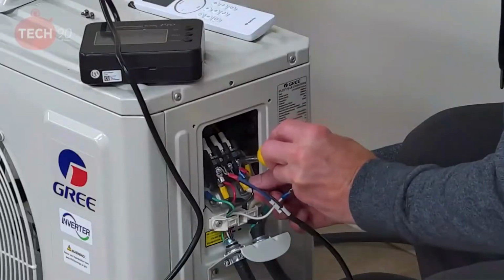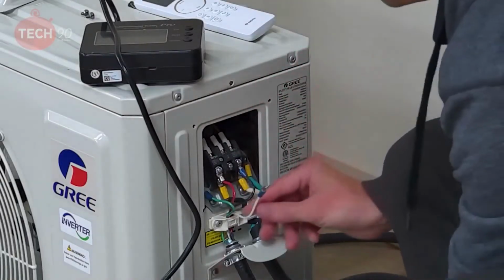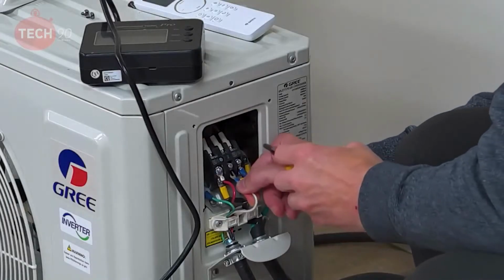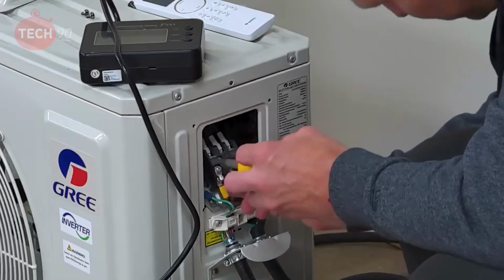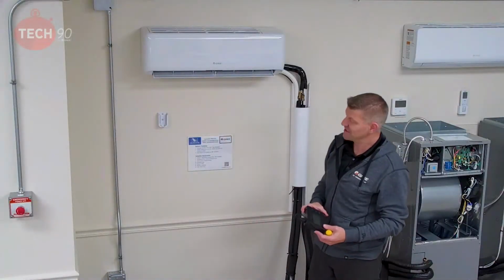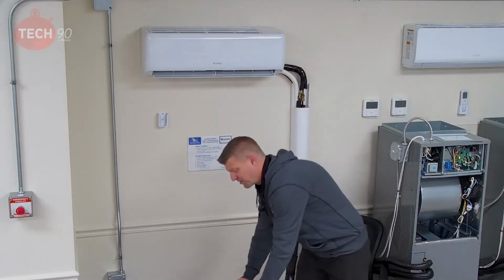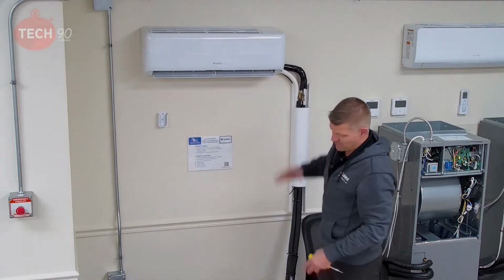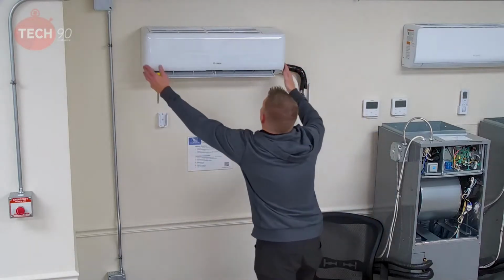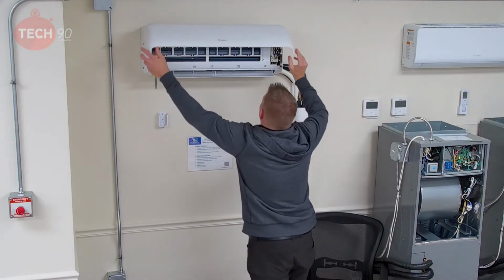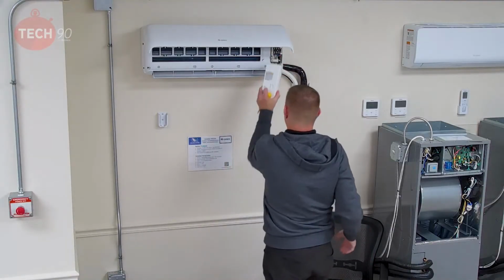Now we're going to disconnect the testing tool from outside. Reconnect the number 2 that we disconnected earlier. We verified that the outdoor unit does not have any issues causing the E6, so we're going to hook up to the indoor head. We're going to simulate the outdoor unit and bring on the indoor head. So what we're going to do first is lift this cover up. Did you know you'd have to take this cover off right here? Already took that cover off.